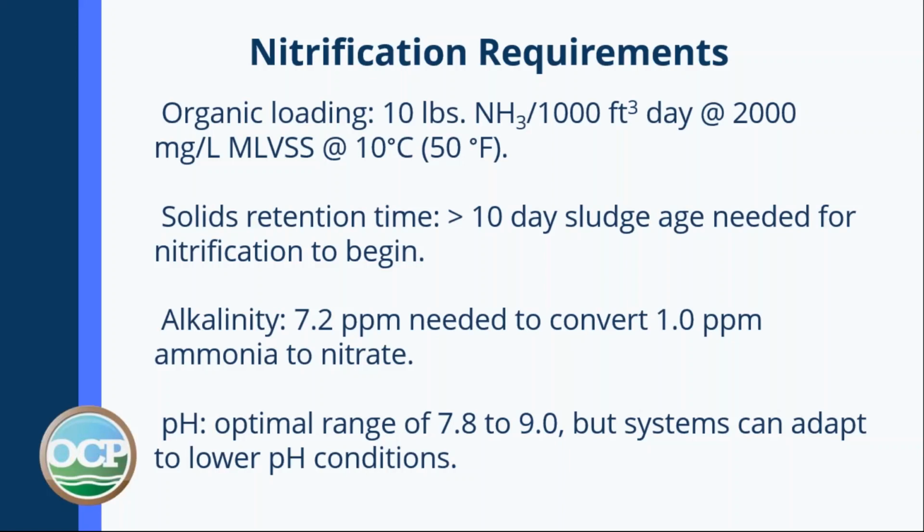The optimal pH range for nitrification is 7.8 to 9.0, but systems can adapt. These bacteria can adapt to lower pH conditions, and you can get adequate nitrification at the 6.8 to 7.2 pH that's recommended for BOD removal.